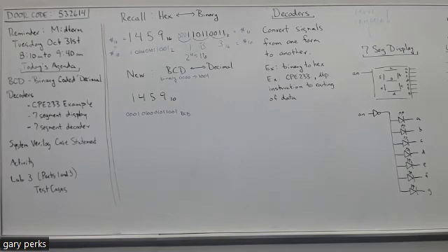So you see what this decoder is doing, and the reason why it's called a decoder, is it's taking some of the bits of the instruction. It's not taking all 32, okay, but it's taking maybe 10 or so. It's taking some of the instruction bits and converting them into select bits for muxes.